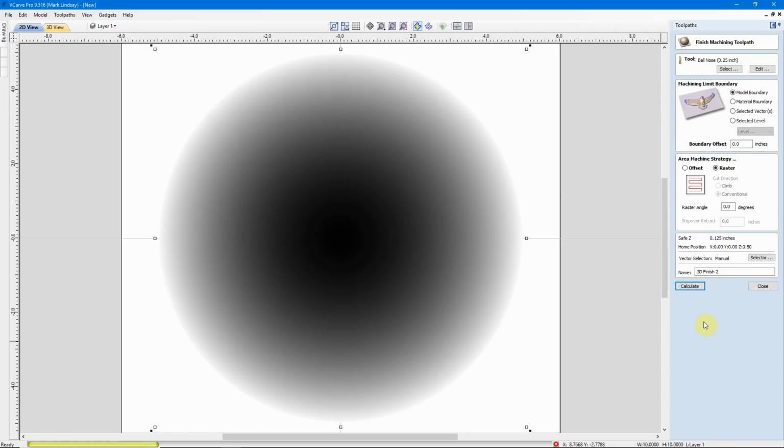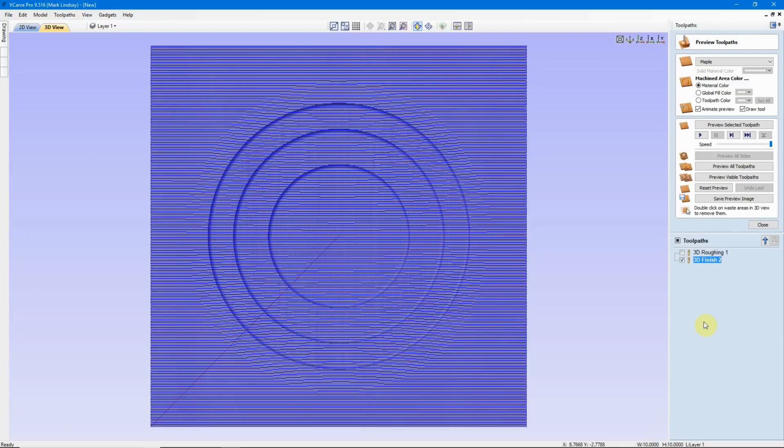And now you want to talk about some slow calculating times. This is when it is slow. The roughing wasn't that bad. This is actually going fairly quickly because I'm using such a large bit. If I were using a 1/8 inch bit, it would be a lot slower than this. Imagine if I was using my 3/64 bit. Now I'm running this in real time just to show you how slow some of these calculations can be when we're using high modeling resolution. Almost finished. And there we go.